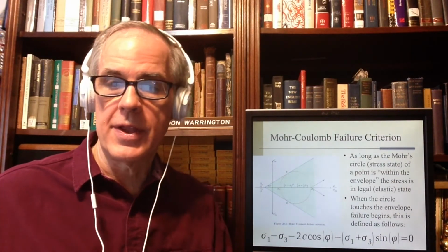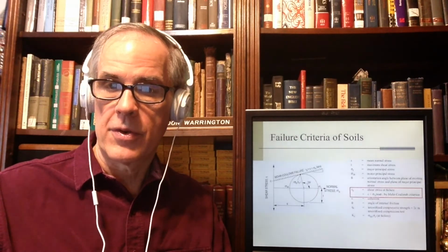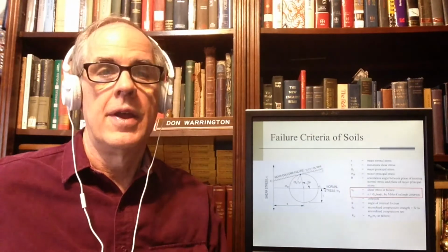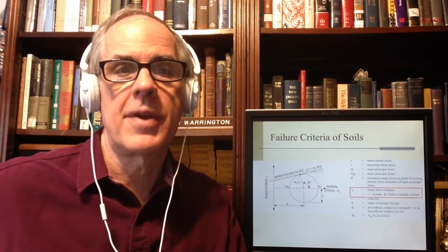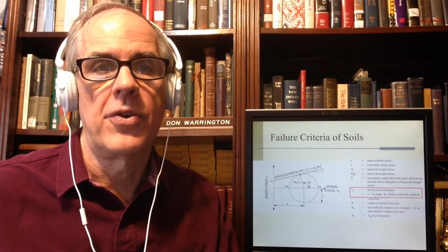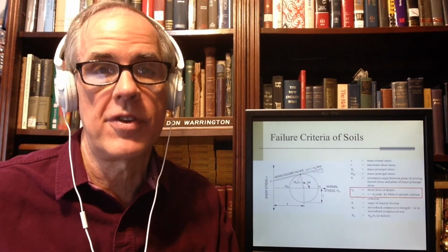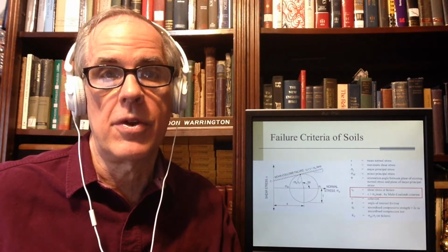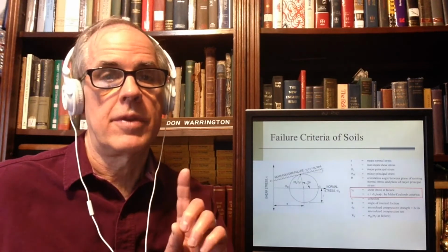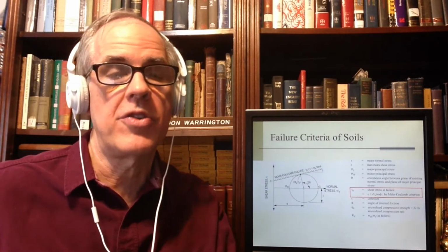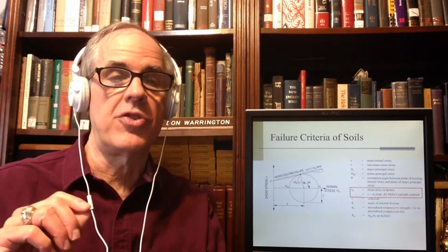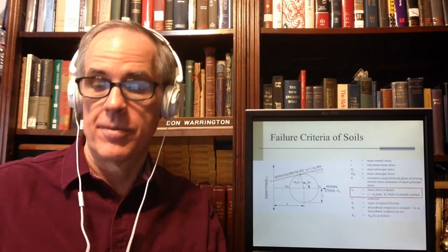And you'll notice that in classic Mohr-Coulomb theory, the strength here is equal to sigma, the normal stress, times the tangent of phi. What that means is that unless there's some kind of external pressure on the soils, cohesionless soils have no shear strength at all, even if they have a positive phi, which they usually do. So keep that in mind. For a cohesionless soil, the strength is due both to its internal properties and the pressure, usually the effective stress, that is applied to the soil.